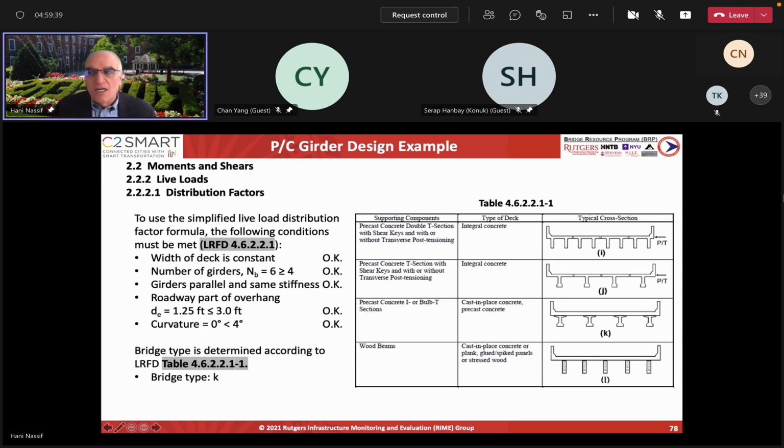So that variable spacing, it depends, people can use the average of that. However, if you're doing it where the maximum moment is, then the distribution has to follow the spacing where the truck moment would be. That's how, academically speaking, I resolved that, and we solved it in one of those questions.